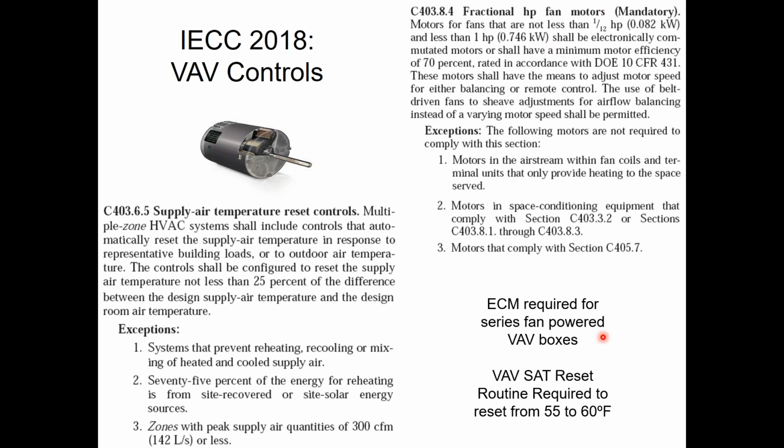If you have a series fan-powered box, the 2015 and 18 codes will require you to put an ECM motor on the series fan-powered box. You will not be able to achieve the requirements of this code spec if you put a PSC blower on there. It's got to be an ECM.